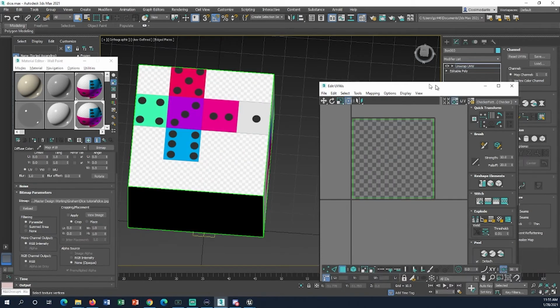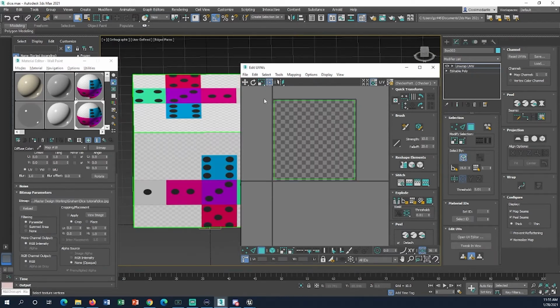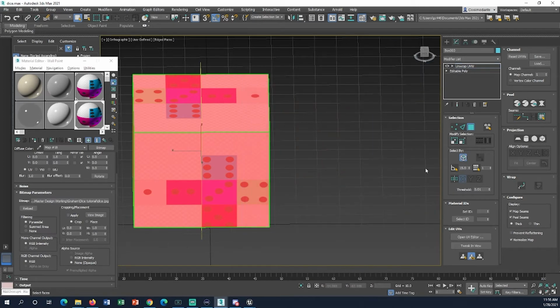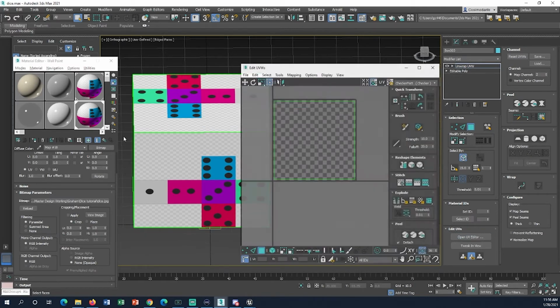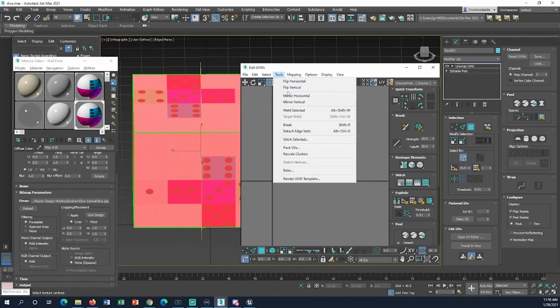So if I want to get as high resolution as I want and I want each one of these sides to be the exact same, I can leave it like this. But if doing so, I have to change my channel to number 2, because the Unreal Engine will read your second channel as the light map channel. And if you don't have a second UV channel, it will just basically take your UV1 channel. And that's why we don't overlap our UVs.